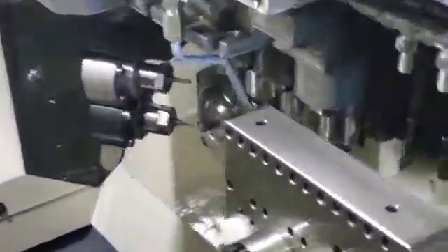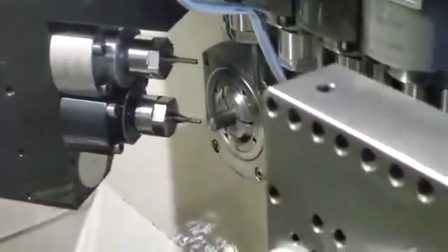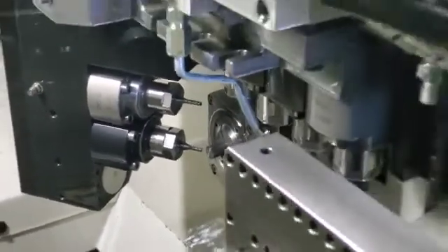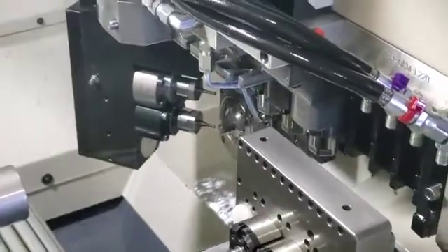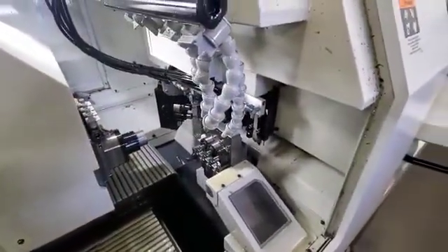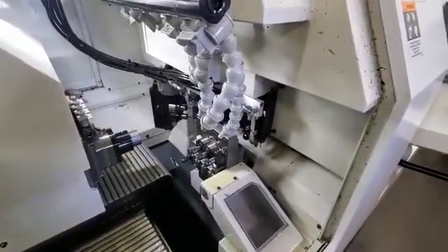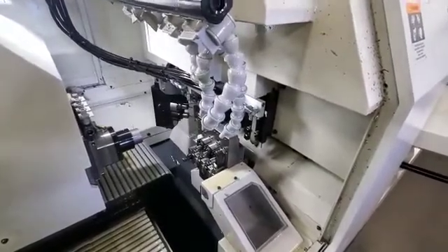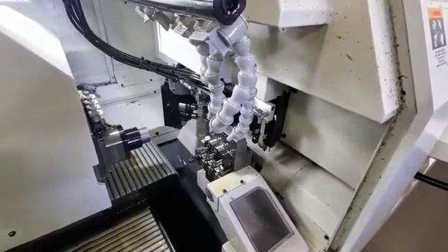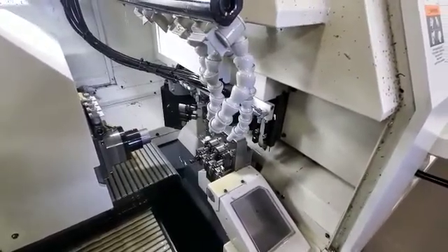At this point, it says to tighten the tool. It pulled off of that stock, and now we're going to get in there with our wrenches and tighten the tool. All right, the tool is tightened down. We're going to put our oil line back. Now, once we hit cycle start from here, it's going to actually do an auto cutoff and start position for you and start to run your part. Then from there, you just watch the tool come in.